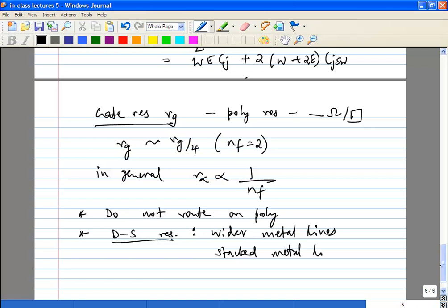We are saying that either the modeling itself is not there, or you just selected the wrong switch. These kinds of parasitic capacitance may not be something you care about. Remember that everything you extract only increases your simulation time as you do the LPE. So there may be certain small parasitic capacitances which you don't care about.